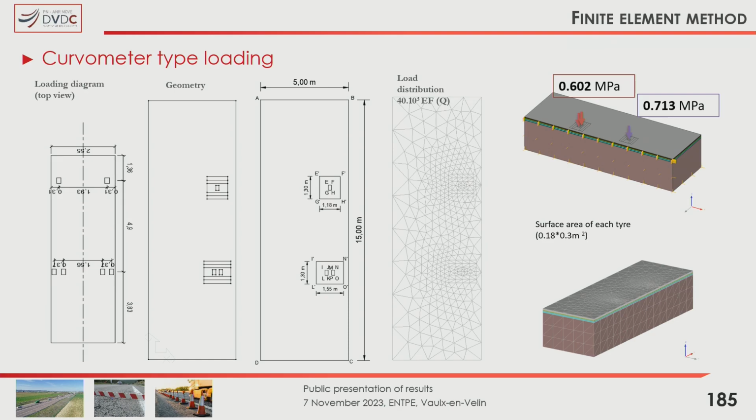We look at short cracks of 1 meter or even sometimes 2 meters for the back axle, and then this allowed us to look at the delamination between different layers at different depths. And we look at the finite elements and the different intensities of loads in this grid.